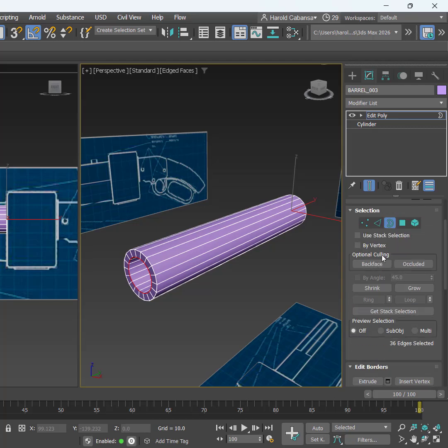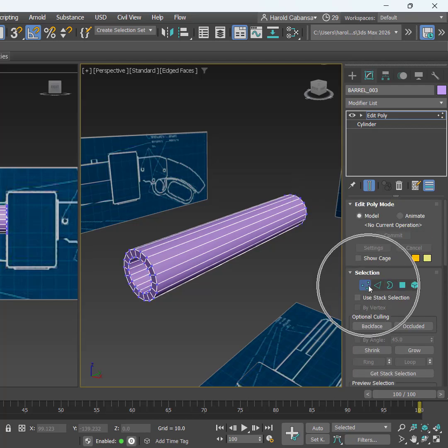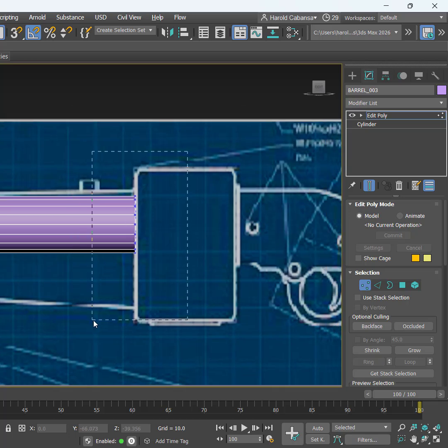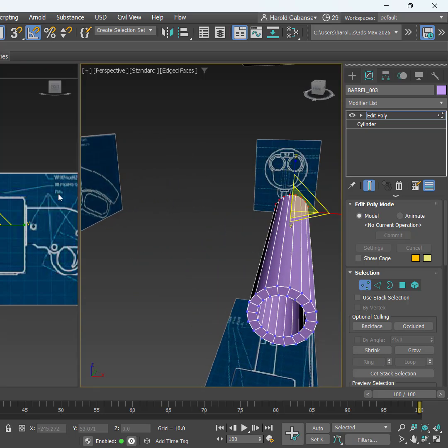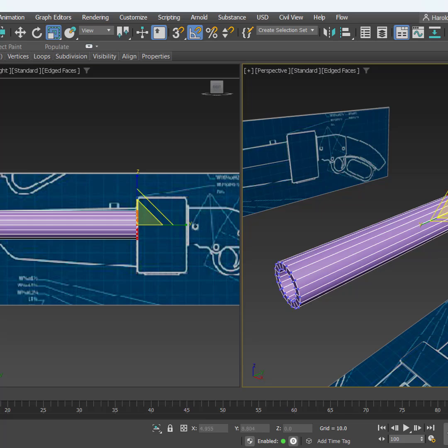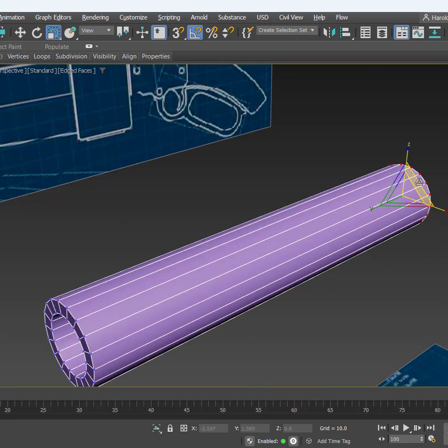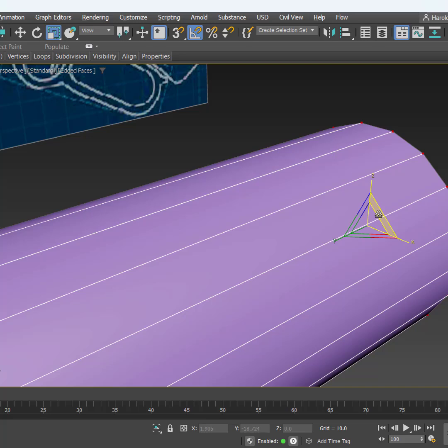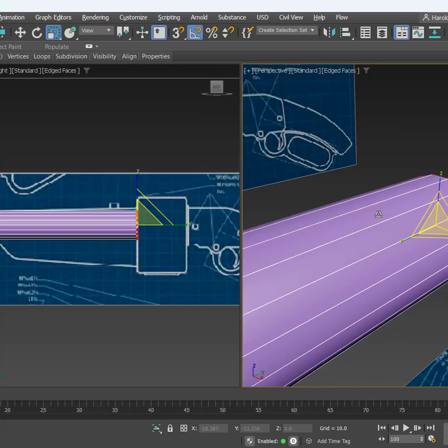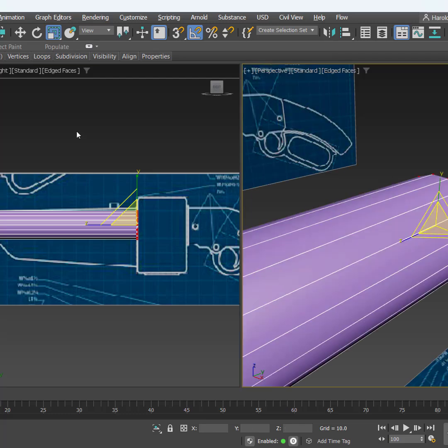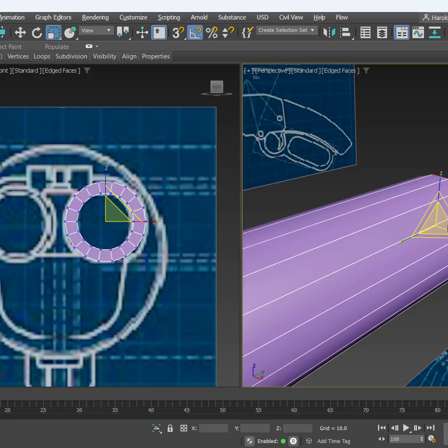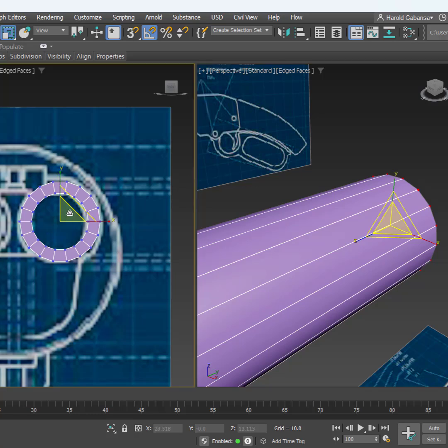So what I'll do is I'll switch to the vertex selection, and then I'll select the vertices at the back, and then I'll press R. Here, on this side only of the X and the Y, carefully, I will start to drag so that in the front view, Shift Z here, in the front view by pressing F, you can actually see what's going to happen if I drag it along here, there.